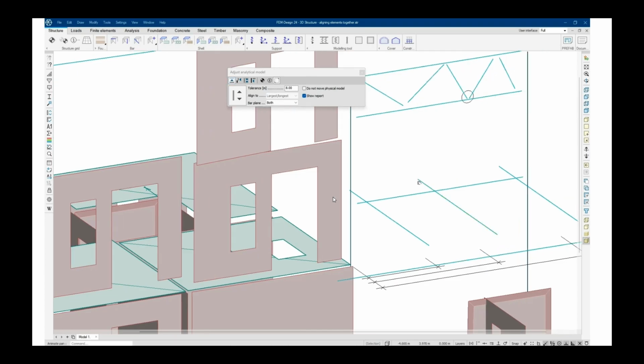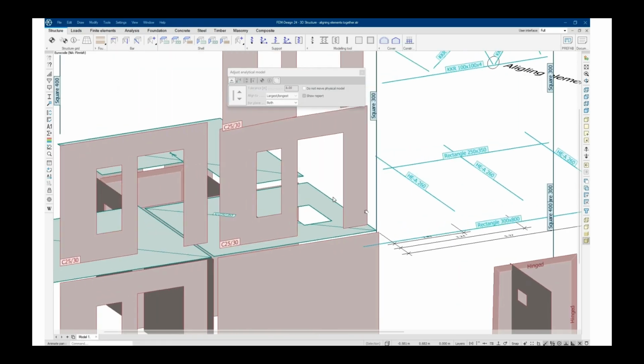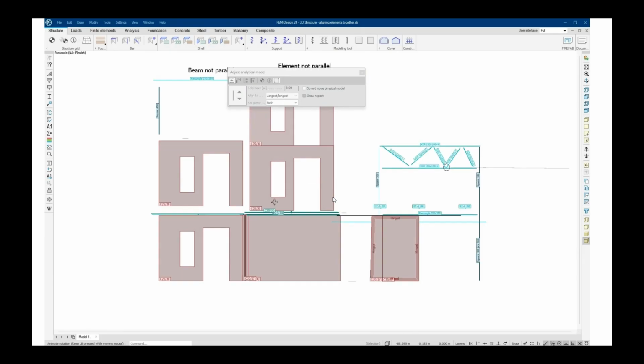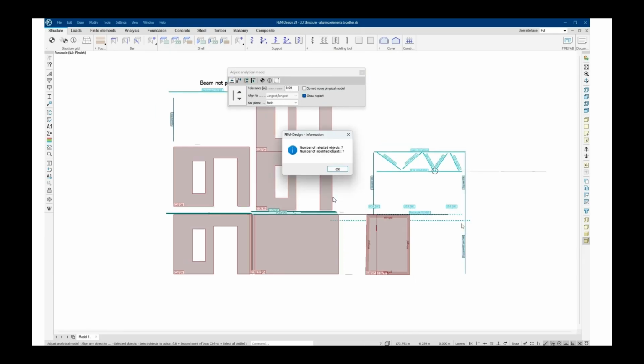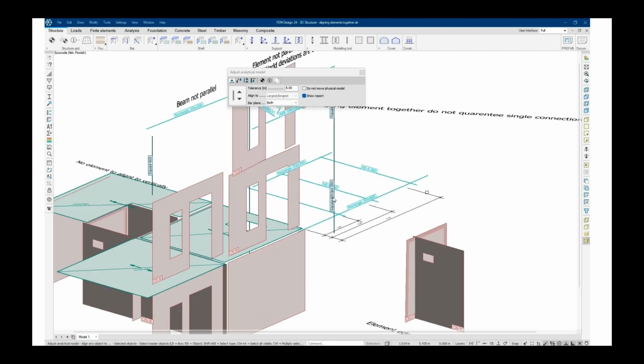So we set the floor as a master. And now we also have to consider the distance of the objects from the master. So that's why we put a really high tolerance. And then we just select which should be on the floor plane. And now everything is also flat height-wise. But please notice that the floors have to be perfectly horizontal. If not, it does not work.